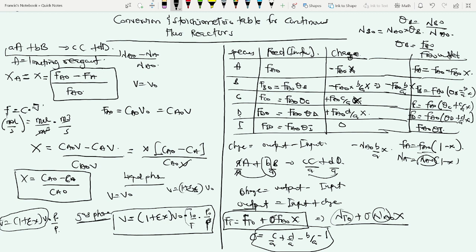And our epsilon, we said, is equal to the initial mole fraction of the limiting reactant times sigma, right? And then we know sigma from this. Yes, so now we know this, and then we can find this. So if the feed is entering as pure A, that means the mole fraction of A is 1. We can find epsilon, and then that can help us to find this.